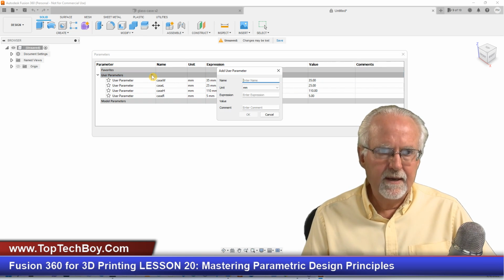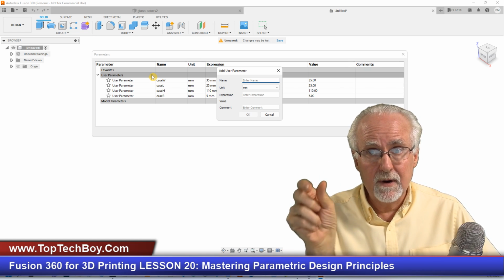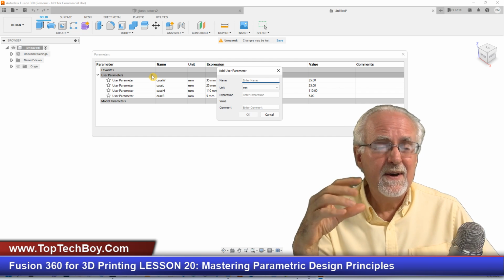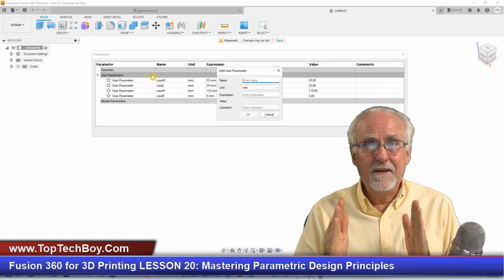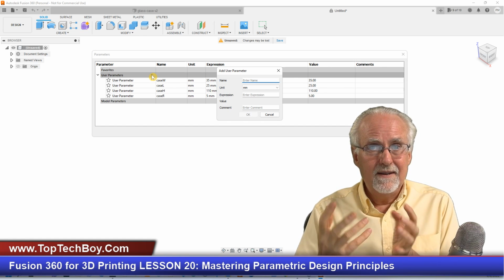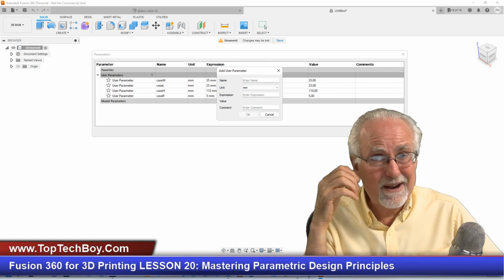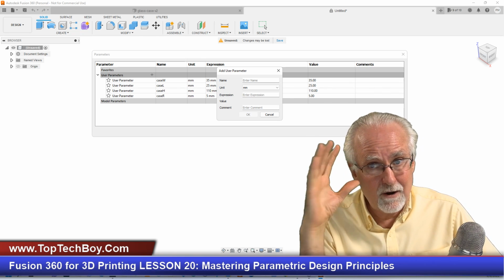Now I'm going to do a driven parameter, and that is the thickness. I could make the wall thickness 10% of the width, or 10% of the length, or 10% of the height. But then if I had something that was 25 by 50, the wall thickness would be different than if it was 50 by 25, which would be exactly the same case, but now the wall thickness would be different. So I want a parameter that I think of as an overall dimension. I'm just going to average the width, the length, and the height, and that's going to be my overall size parameter.